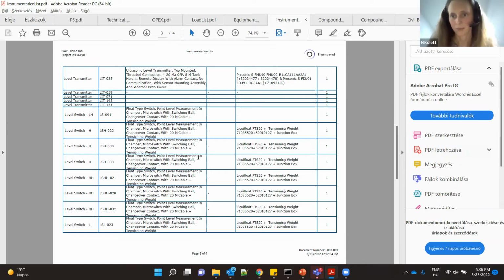But if the model says that with that specific SRT the system will not work and the effluent limits are not met, then we drop the user input SRT and increase the SRT until the system is able to meet the limits. These are the things we do to make sure that the system will function properly.